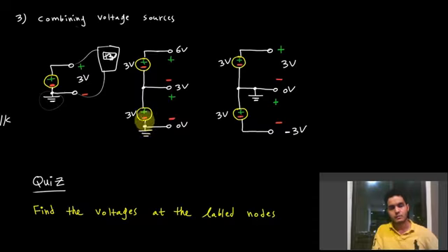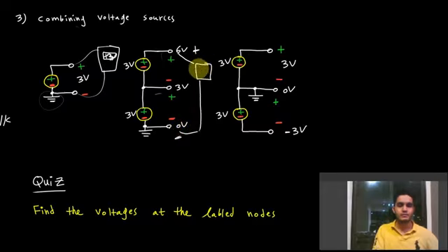It's grounded at the negative terminal here. You have some terminals going out of here. Locally, if you were to measure between here and here, you would have a 3 volt drop here and a 3 volt drop here. But as you have grounded here, if you were to put the positive probe of the multimeter here and the negative probe here, what you would actually see now is 6 volts, because you're adding these 2 voltages. You rise 3 volts and rise again 3 volts, and you get 6 volts in total.